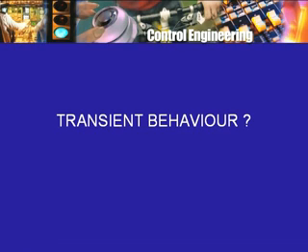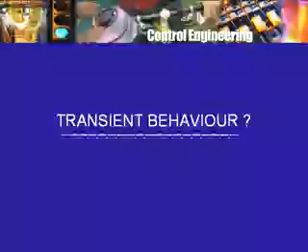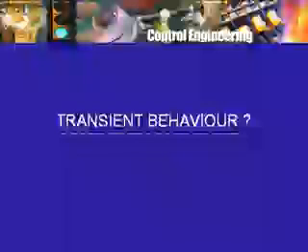Of course, the series resistance has ensured that the starting current was sufficiently low, but one would like to know what will be the behavior during what is called the transient period, or what will be the transient behavior, something that does not stay on for a long time but is there anyway, when you make a transition from zero condition, motor at rest, to motor running at the desired speed.